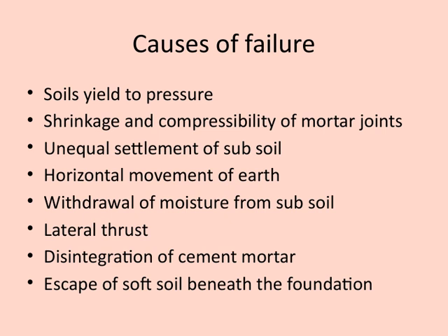Unequal settlement of the subsoil is another critical factor. When different parts of the foundation settle at different rates, it creates stresses that can damage the structure. Horizontal movement of earth is also a common problem. Lateral shifts can exert force on the foundation, compromising its integrity. Withdrawal of moisture from the subsoil leads to drying and shrinking of the soil, which can cause the foundation to settle unevenly or even crack.